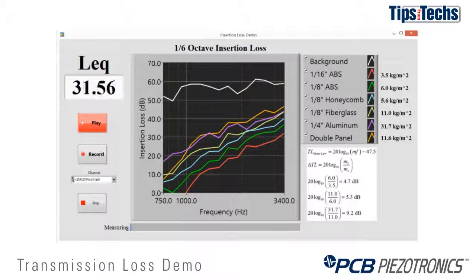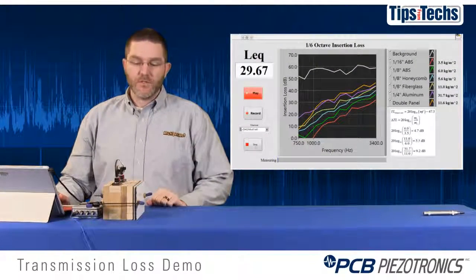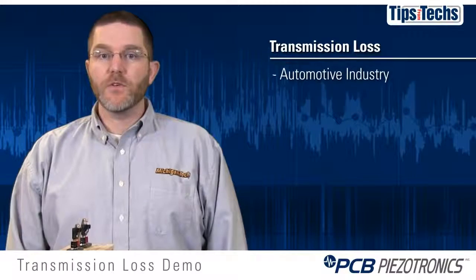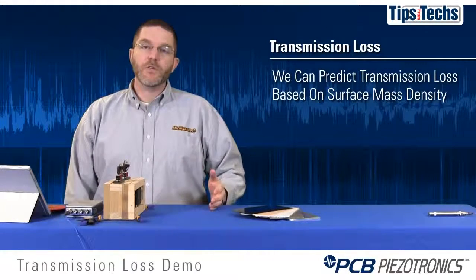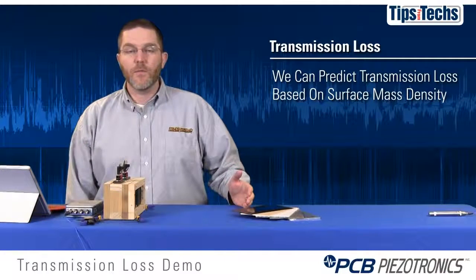So you can see we get considerably better insertion loss with a double panel system, and that's because of the air gap. So in future demonstrations, we'll talk about double panel systems and the theory behind those. So transmission loss is a very important factor in the automotive industry, as well as the aerospace industry and building acoustics. And in conclusion, what we saw in this demo was that we can make a very good prediction of single panel transmission loss using just the surface mass density of the panels.